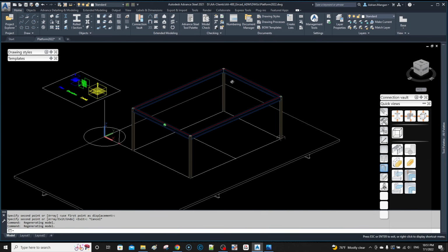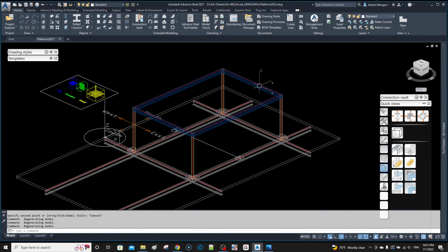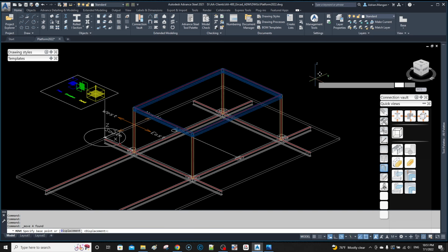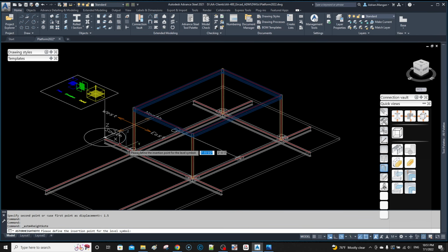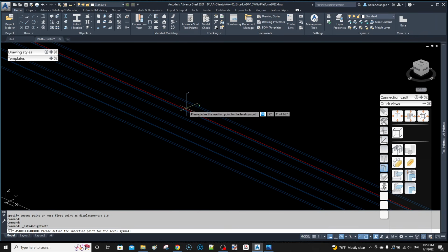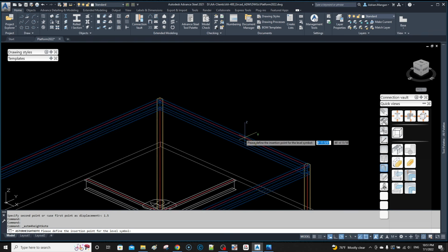So I guess you want a couple of more beams there. What we're going to do first is move this down, because I want my stairs to be coming off on top of the grating. I'm not going to get too technical with this. The stairs I'm not going to get into too much, but let's just keep the height something simple like 12 feet. So let's move these down 1.5 inches, and then if you just want to check them, what did I do down here? 60 feet plus 12 is 72, minus an inch and a half is 71, 10 and a half.